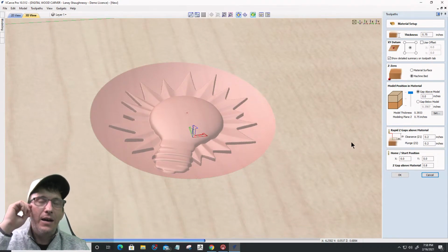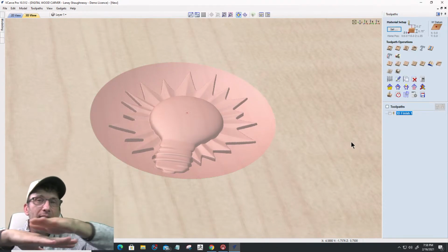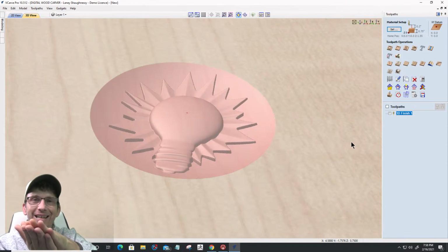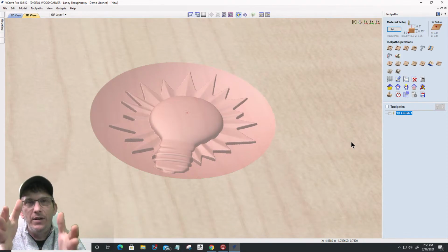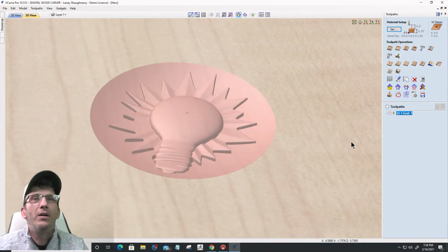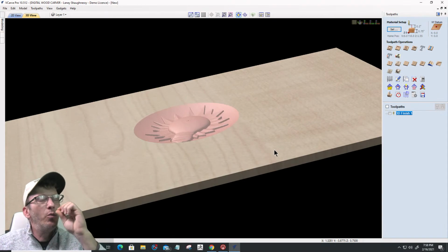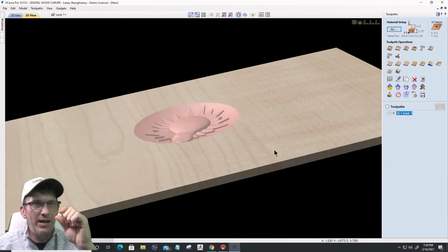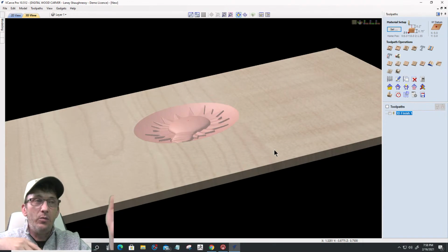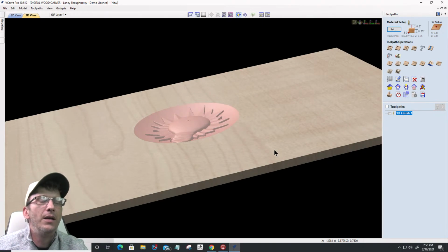But I also may have a 2D model where there's two-sided, and I need a zero plane in the middle. I need to create some meat in the middle. So a zero plane could be added in between side 1 and 2 and given some meat, so I have a two-sided model. I might want to plump it up and create some meat without having to add base height to each of my models. So with the zero plane, all it does is it adds a surface of material with a zero height, and we can utilize that to kind of fill in the areas, especially when we're doing something that doesn't have any background around it, and we need that so the model doesn't cut beyond.